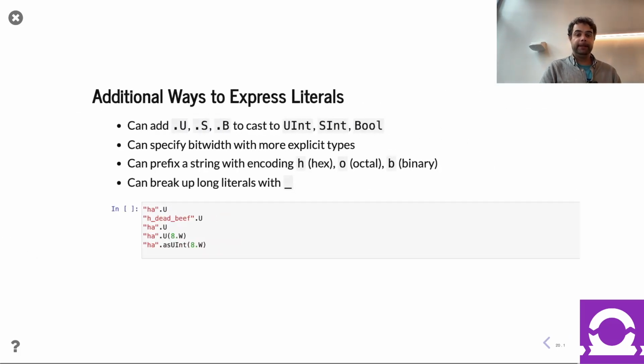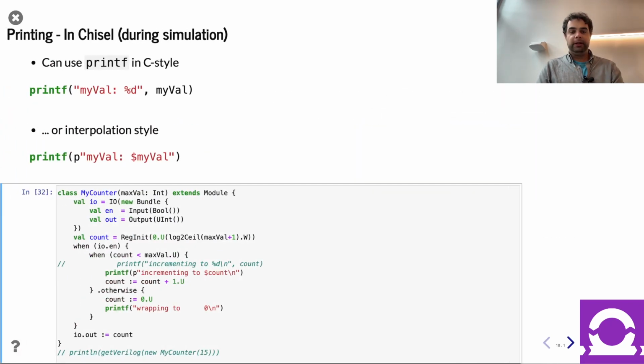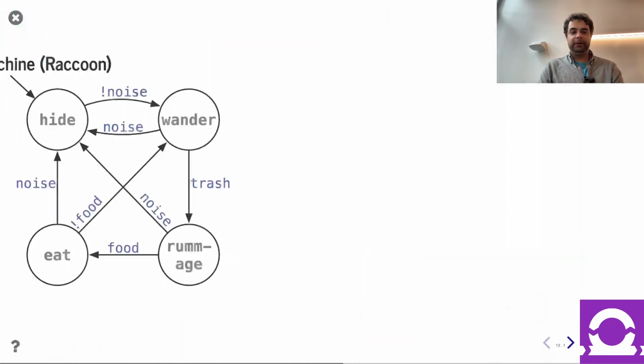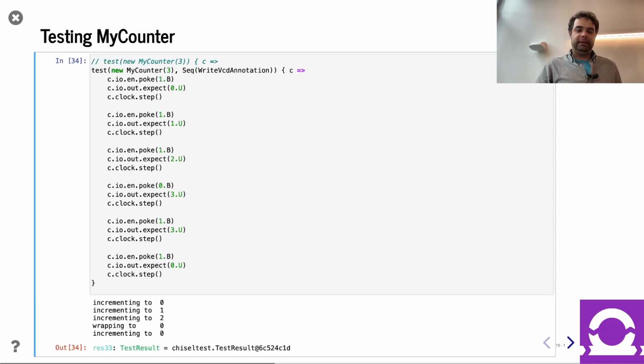Okay, so then, actually before I do literals, I'm gonna go back and let's do waveforms. So how do we get waveforms? Well, if we go back to our earlier counter test, I can say, hey, why don't you write the waveform? So this is a little bit clunky syntax, but yes, you can basically say, write the VCD. And it did that. Now you may be saying to yourself, okay, where is that VCD? That VCD is lurking